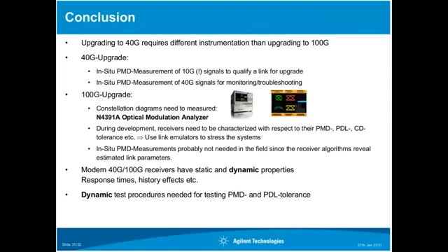We think that in-situ PMD measurement is going to be needed when upgrading to 40G. It surely would be helpful to also measure 10G signals with the in-situ PMD measurement approach, and we are working on that.